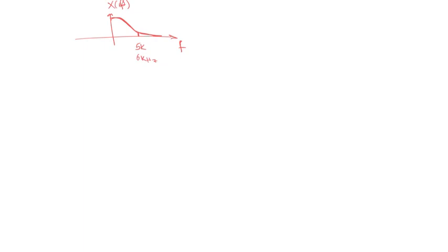So how do you do that? First of all, you have to take that signal and divide it into those 3 pieces, so that you can control each piece independently. And then at the end, you have to combine them back to retrieve the original signal after being affected by that amplitude change, okay? So you have your voice, which is a time domain signal, that's X of t.